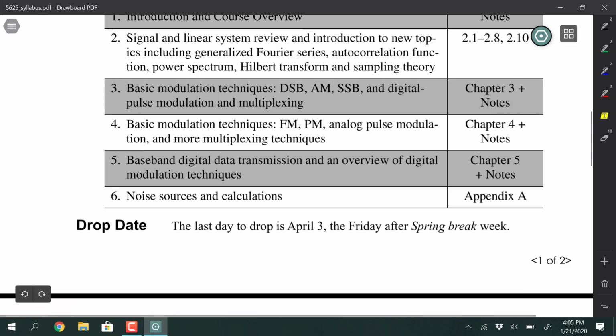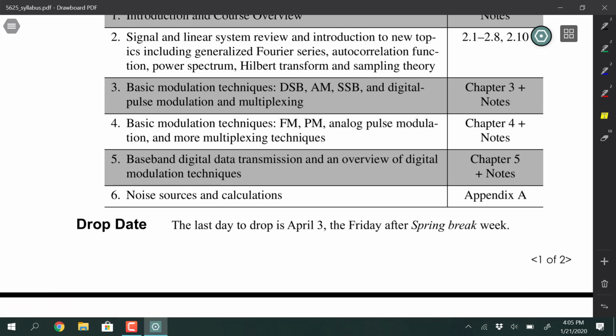And in your first simulation project, you'll also get exposed to multi-rate sampling, because that's a key part of software-defined radio too. You come in at one rate, then you do some processing, and then you downsample, and then you do some more processing, and you might downsample again. So multi-rate processing, which is part of digital signal processing, formally gets introduced in the first project, just so you can lay your hands on it and play around with it a little bit.